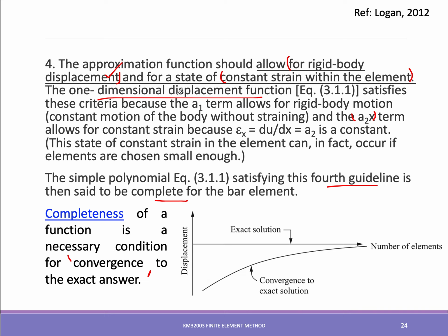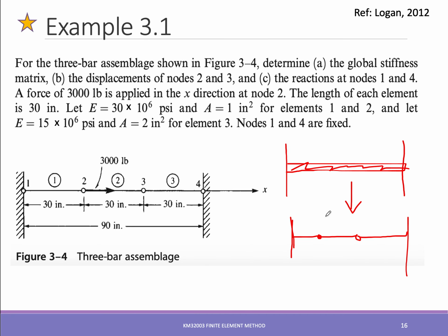When we start to derive or to select the displacement function for any type of finite element, you can see that the convergence of the solutions towards the right answer, or the exact solutions, becomes closer and closer as the number of elements increases. So in the previous examples, where we used 1, 2 and 3 elements, if there is a force acting, or maybe the weight acting, we would expect this kind of characteristics of displacement later on, right?